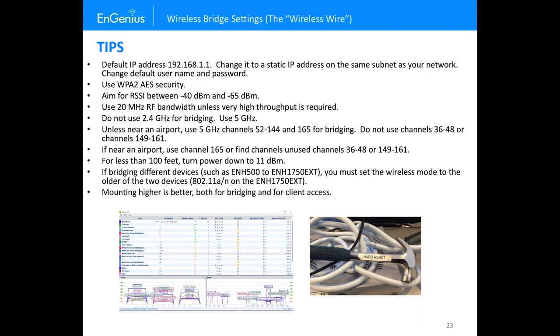You're just being a polite unlicensed user for 5 gigahertz. If other people do it, everybody benefits. It actually benefits yourself, because then you have less interference to yourself. Especially if you do a large deployment of these point-to-point, point-to-multipoint, you're going to raise the noise floors. You want to minimize how much you raise the noise.